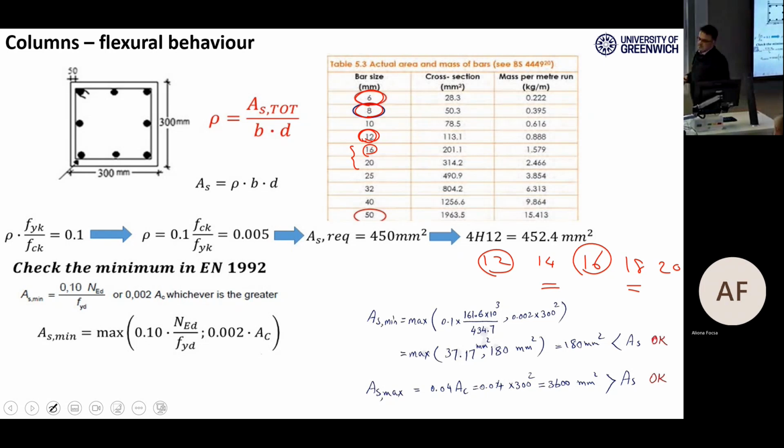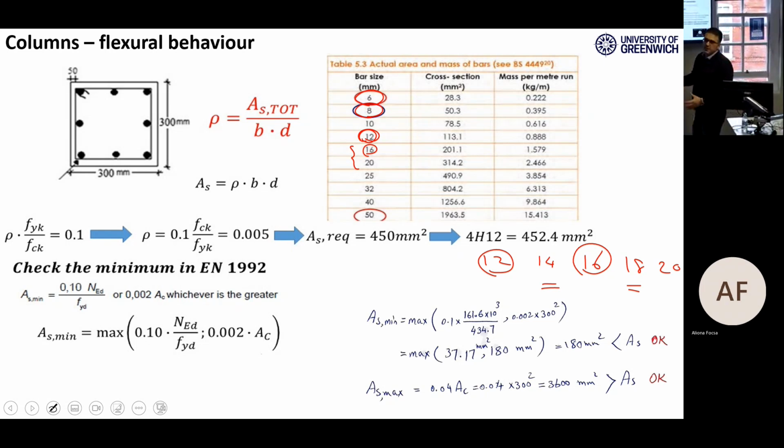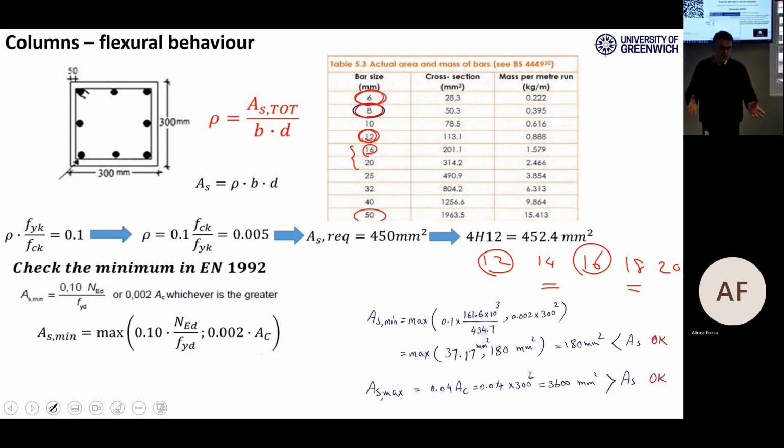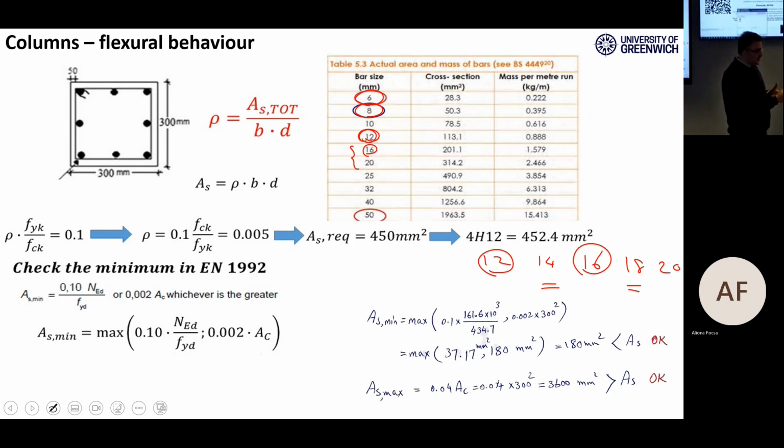Absolutely correct, yes. Because in the project, when they bring these rebars into the site, it's very difficult to differentiate between number 12 and 14 with your eye, intuitively. So it's likely to make mistakes for the workers. You use 14 instead of 12 or 12 instead of 14, right?